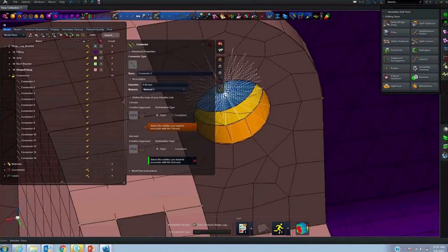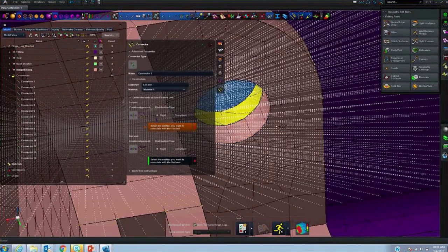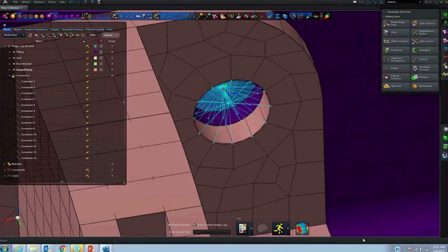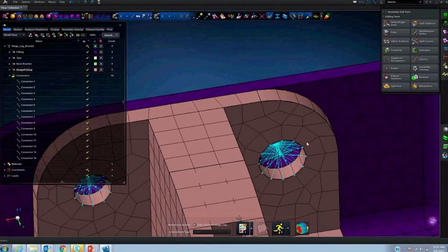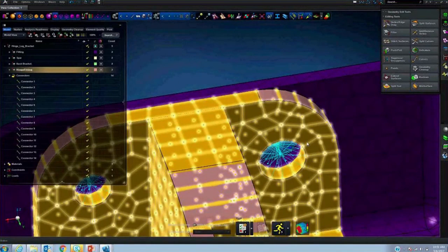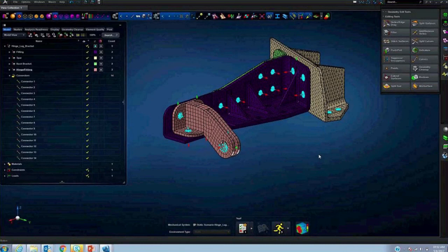3. Now, since we made the whole diameter as 8 millimeters, now we can go and modify the diameter of the bolt 8 millimeters. Now, pretty much, you updated the geometry, updated the bolt, and now it's done. And what is next? You can check the context, run the simulation. Now we can take a look at what will be the connector forces after the design modification. So it is that easy and that innovative and that interactive to make any design changes looking at the section forces through any of these connectors in this example.